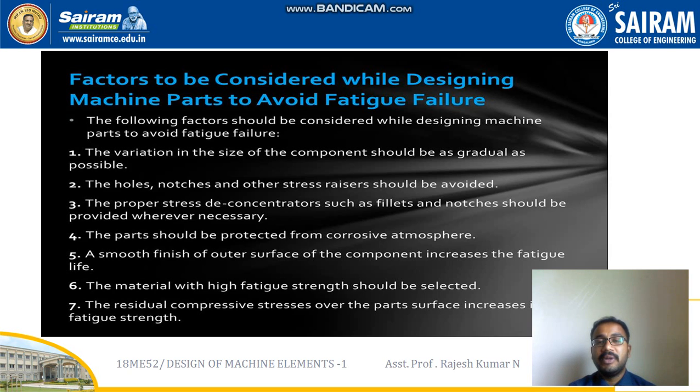As we discussed previously with the different types of loads, we had the concept of yield stress, or yield point, and ultimate stress, or ultimate point. When a load is applied on a metal body and it crosses that yield point or ultimate point, we call that body a failed metal, since it is losing its contour beyond the yield point and ultimate point. But fatigue is something where, before reaching its yield point or ultimate point, the body fails because of repeated or continuous loads.